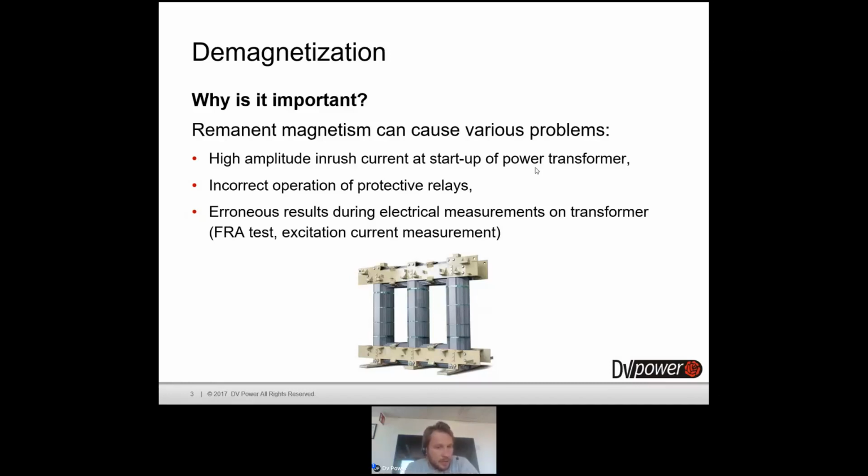It's important to check that during transportation, which is a very tricky job, there is no kind of mechanical stress or damage in the transformer that can be fatal for the substation or transformer. One very good test for inspection of mechanical problems in the transformer is the frequency response analysis test.